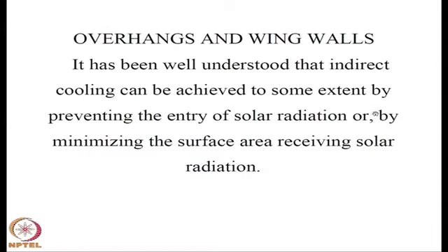So, in that context, the solar radiation available to you above a particular critical level shall not be utilizable to heat the room, because it overheats beyond the comfort condition. The concept is the same, the methodology of calculating phi bar remains the same. However, that energy is not useful for contributing to heating the room, because it overheats.